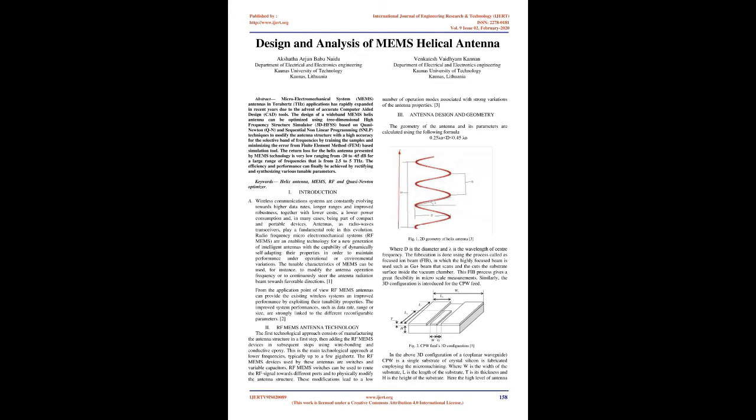The design of a wideband MEMS helix antenna can be optimized using three-dimensional High-Frequency Structure Simulator, 3D HFSS, based on Quasi-Newton, QN, and Sequential Non-Linear Programming, SNLP, techniques to modify the antenna structure with a high accuracy for the selective band of frequencies by training the samples and minimizing the error from the Finite Element Method, FEM, based simulation